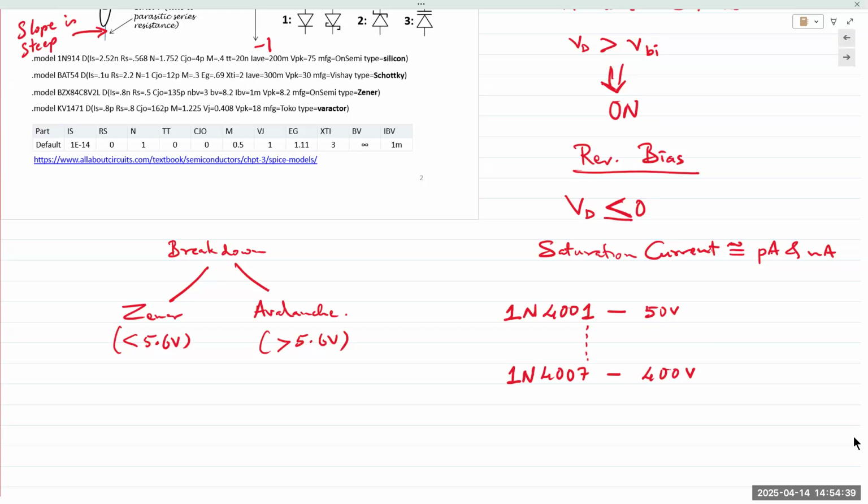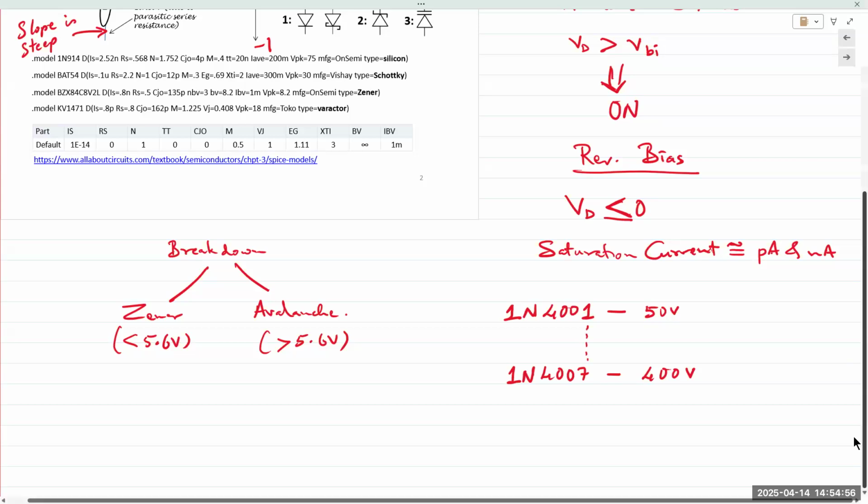In intrinsic material, the electrons hop free or are removed from the lattice structure due to thermal energy that is acquired. In reverse bias, the electric field is supplying that energy. Electrons acquire that energy and are now popped free. These electrons are now accelerated across the junction. So you have holes and electrons being created on either side of the junction. They are now accelerated across the junction, so you have current flowing in the opposite direction.